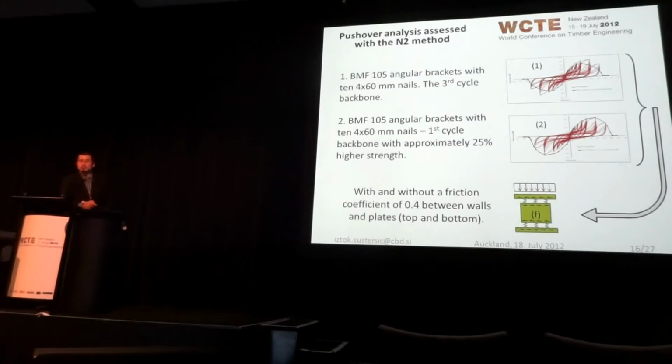I think to keep on the safe side, I would stick to 2.0. I think that's also the value that's in the New Zealand code that's prescribed for timber structures. So I'm guessing that they've done some more analysis generally, because we're only dealing here with brackets. So it's not that we have the nails or anything. We just have to make sure.